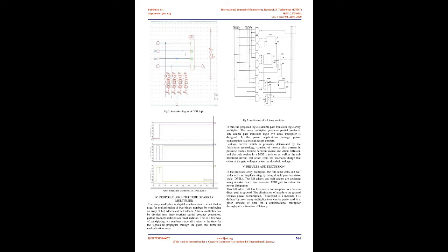The existing EXOR gates are simulated using Mentor Graphics tool with the voltage of 5V using 130 nanometers CMOS technology. The transient analysis of the circuit results is shown with the voltage of 5V. By using NMOS and PMOS transistors in the EXOR gate, the power dissipation is more because a greater number of transistors are used in the design. As the transistor count increases, the power dissipation also increases.